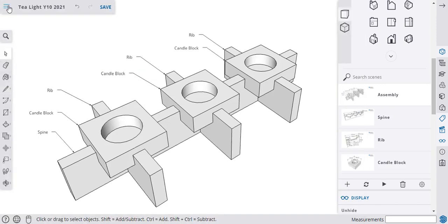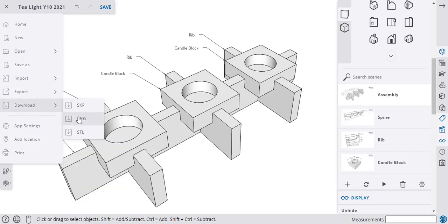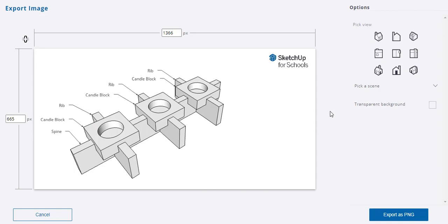And let me show you that. So if I were to export or to download, it's a PNG, I keep getting mixed up, it will download this entire file, which is going to often be longer than it needs to be high, and it'll have this logo. So I not only need to save it to my hard drive, but when I bring it into whatever document I'm working on, I'm going to need to crop and stretch it to fill my page and not have unnecessary information in it. So those are the reasons why I prefer not to use the download, or how it says export. That's why the terminology is confusing. They've changed where it is in SketchUp, and I prefer to just do a snip with a cut and a paste. You can also do a screen dump, in which case you've still got to do the crop and the resize anyway. But that's the basic method for getting scenes and dimensions into a model.